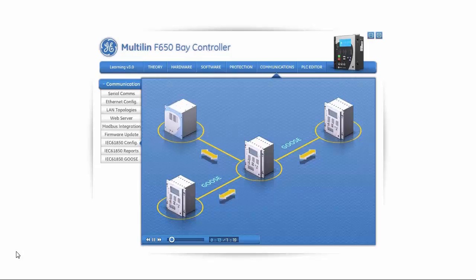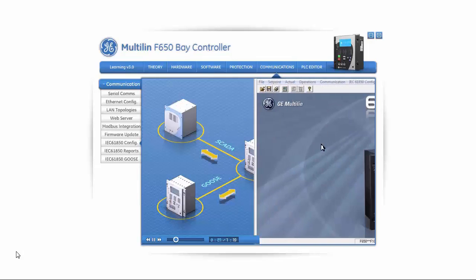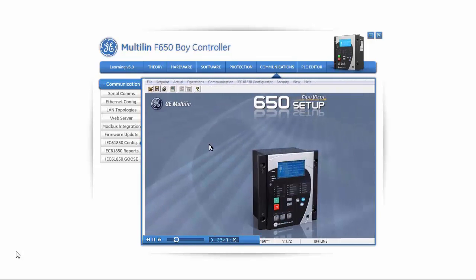Vertical communication. For example, protection relays that communicate with a CCU or SCADA systems. Since IEC 61850 is an international standard, it is accepted among different relay manufacturers, which means that the F650 can communicate with any other IEDs that follow this standard. The F650 relay provides the capability of communicating with other IEDs, SCADA, or CCU systems using this standard.